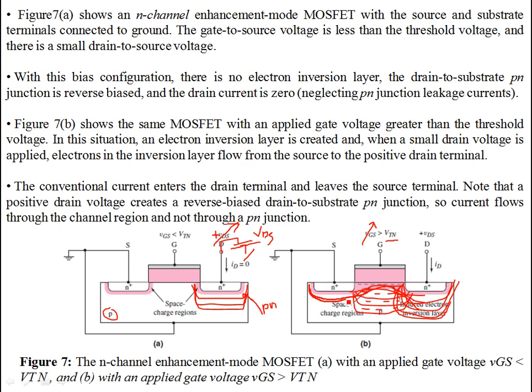The channel is going to have a gradient like this. There will be more charge density around the source terminal and less charge density across the drain terminal. So what happens is that you are modulating, or changing, the conductance of the semiconductor material. If in this region you have fewer charge carriers, you are increasing the resistance of the channel. Call this RC. So this RC increases, the resistance of the channel increases, and the result is a lower ID, the drain to source current.